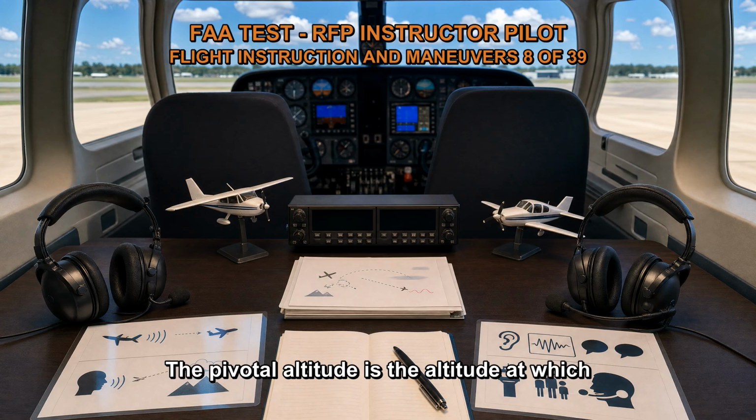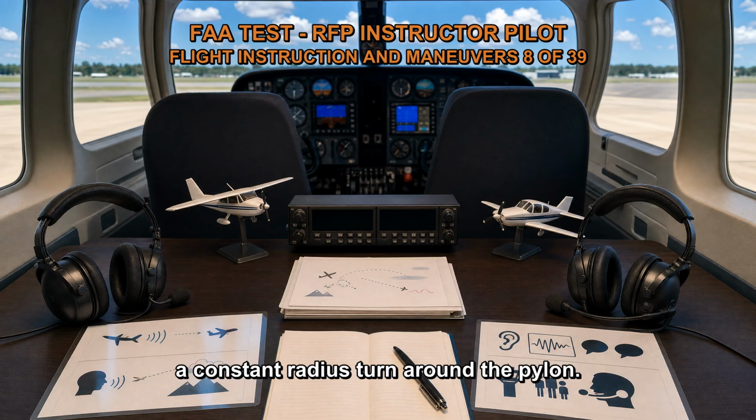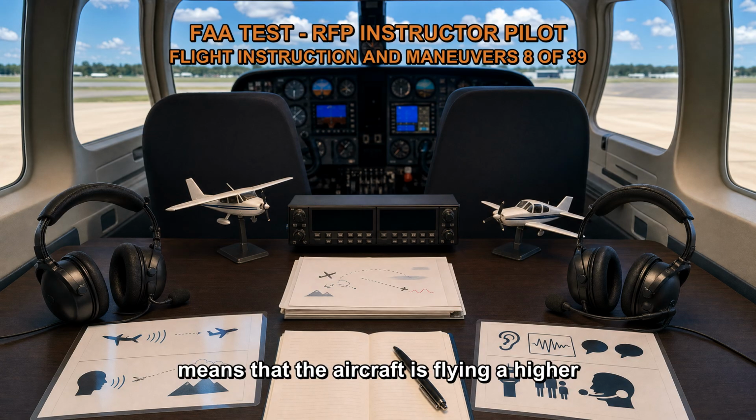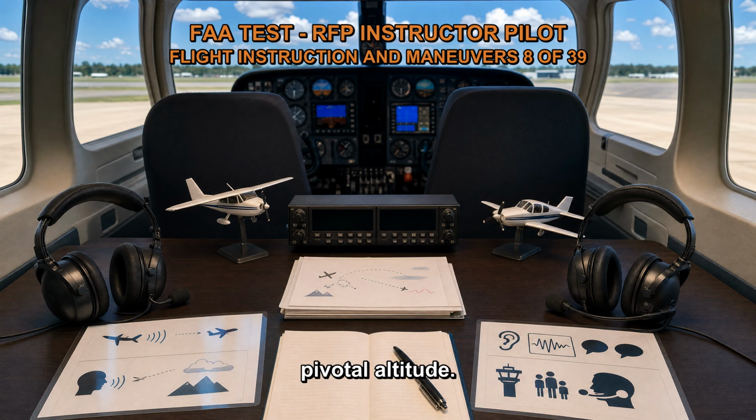The pivotal altitude is the altitude at which the aircraft's ground speed is minimum while maintaining a constant radius turn around the pylon. It is the altitude where the aircraft achieves the most efficient turn. When the wing moves behind the pylon, it means that the aircraft is flying a higher path compared to the desired pivotal altitude. In other words, the aircraft is above the pivotal altitude.